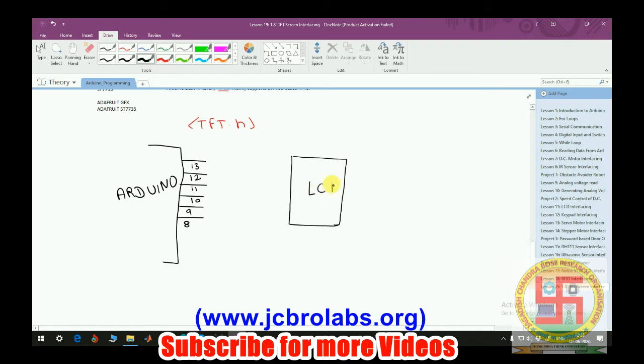The connections are like this: pin number 8 is connected to the reset of this LCD, and then pin number 9 is connected to DC, which is the data or command register, DC or A0. Then pin number 10 is connected to chip select, as we discussed.